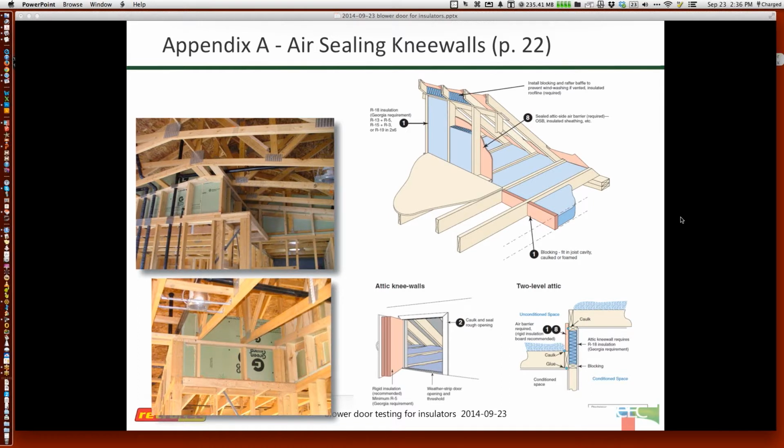So at this point, there's a lot of things that are kind of sealed up in general. Hopefully the windows are installed, and a variety of other openings are in place, and doors and windows. But I now actually have the interior open, but if I have a ceiling, which I'm going to use to put the insulation on in the attic, you can kind of get an idea at this point as to what's going on. If there's even large openings, they can actually be covered with rigid foam board or drywall or something to just find out if there's some really serious issues or challenges with what's happening with the structure at this level.